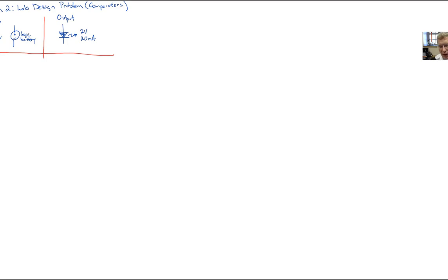So you want to modify your power supply so it turns on a bright LED whenever the voltage on this logic battery goes below 5 volts, because soon after that, your robot's going to act weirdly. You've also got a separate battery that's 12 volts, and you can rely on that being a good 12-volt source. Your output is going to be a single LED. It drops 2 volts, and it runs at 20 milliamps.